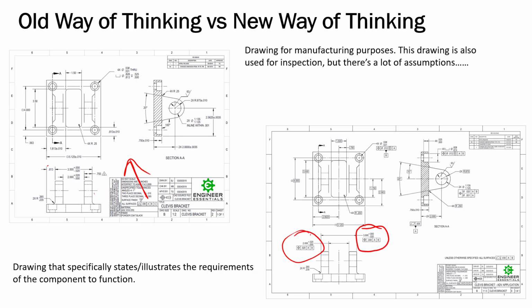So, and that's all of us that have been in manufacturing for a long time. You have to take a lot of gambles when you're dealing with coordinate dimension prints like this on how to set it up and how to inspect it, and what's really necessary for the function of the part. So you're going back working with engineering, and a lot of times quality will try to, if there's no better way, mimic how it was machined, and that's a bad idea. Having this over here is very specific. It's very clear. Lock it down on A first, then on B, then take your inspections. There's no other interpretation to that. So no questioning. We don't need to go back and ask engineering, how are we going to do this?